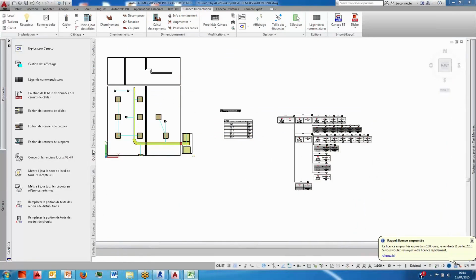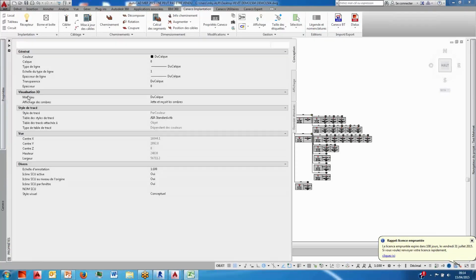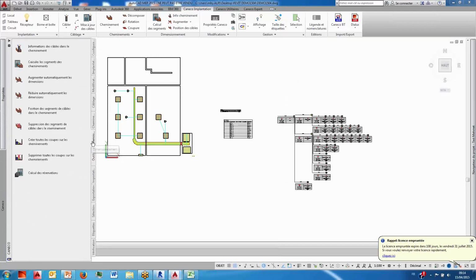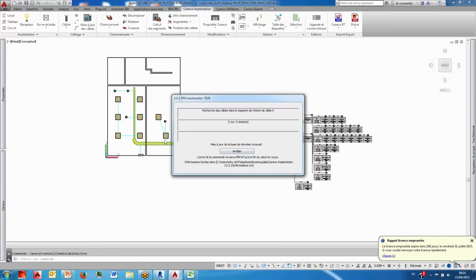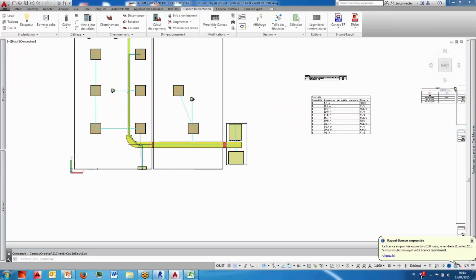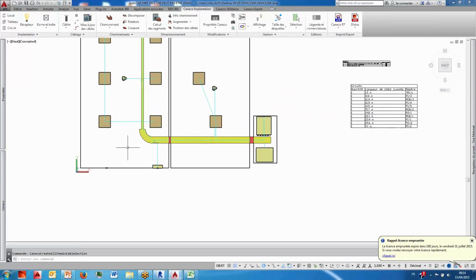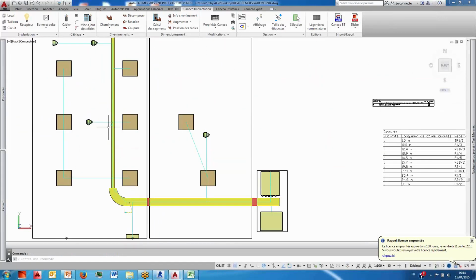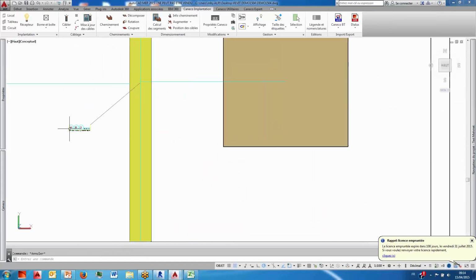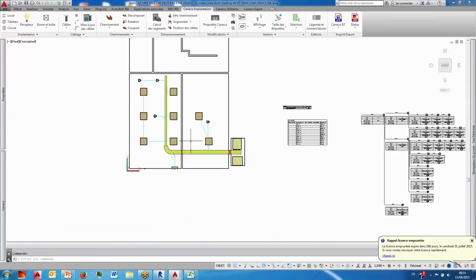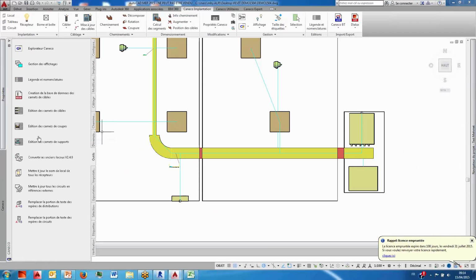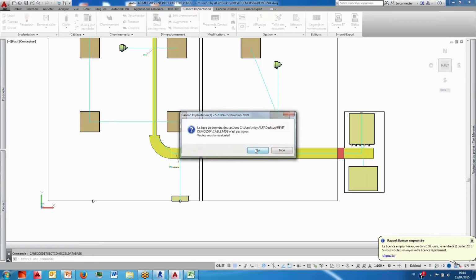And what we can also create, it's a list of all the section that we have. For example, you can just say create all the section on the drawing. It will automatically generate on the drawing all, you automatically generate them. So we have a view of all of them, and this one have been resized, and we can create the documentation related with this view. So we can create a section view.